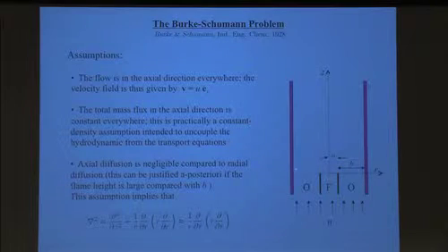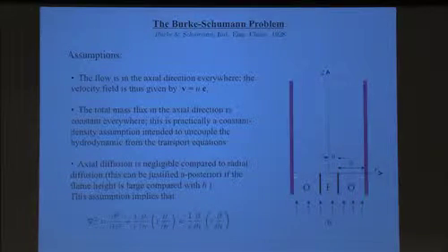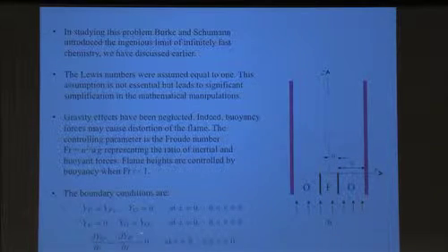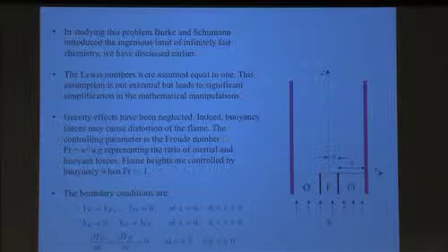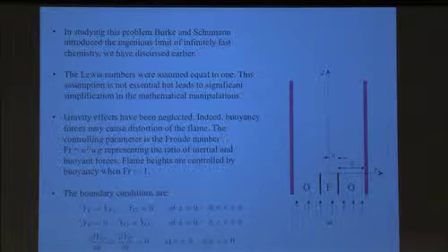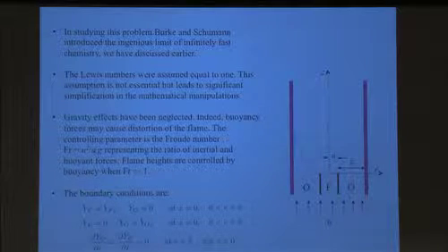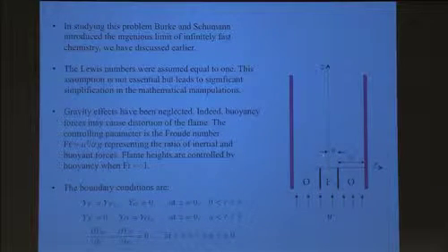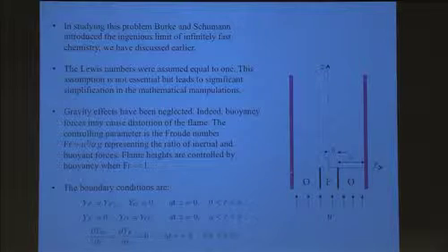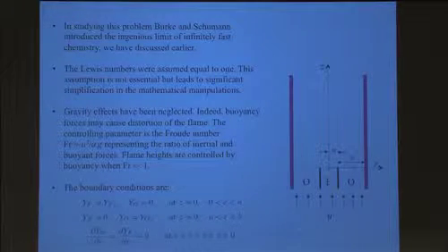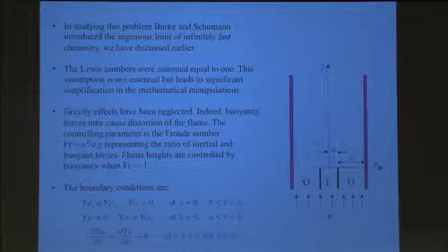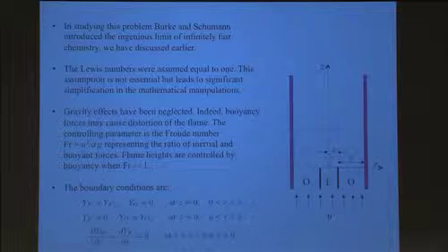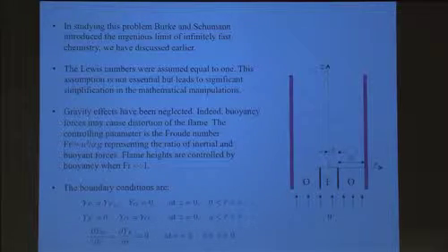You see, if that's not the case, in other words, if you include axial diffusion in the problem, you cannot really impose a boundary condition at z equal to 0, namely at this line here, as I specified. In fact, you have to solve the problem all the way to sufficiently negative values of the axis z. Because if axial diffusion is important, then the fuel or the oxidizer can diffuse backward, right? There's backward diffusion, and it can go as far as the diffusion rate allows, okay? So these boundary conditions are fully consistent with the model that they have chosen.